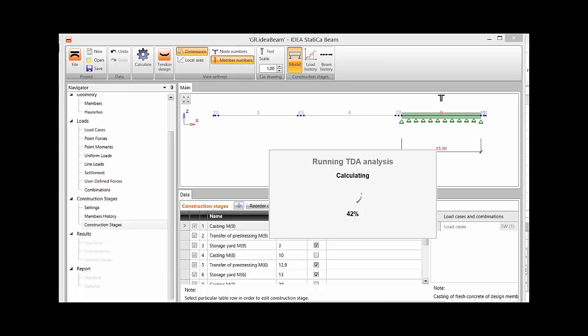The losses of the friction, is there only one value, or is there an upper limit and a lower limit? There is one value for curve and one value for straight path, and we do not have upper and lower limit, unfortunately. I think that's the reason why we have r_sup and r_inf in Eurocode, those coefficients, because in fact you apply this for serviceability limit states.